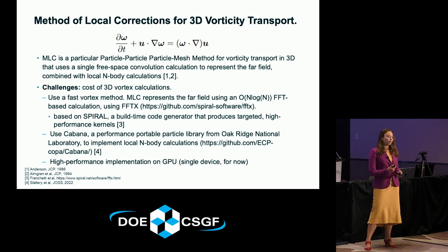And we're interested in solving it with particles. So we have particles carrying the vorticity. We're using a particle mesh method, which I'll call P3M. And this is to address the challenge of vortex calculations. They're quite expensive because you have very many particles. The vortex method we're using, MLC, represents the far field, where you can solve it with an FFT-based calculation.